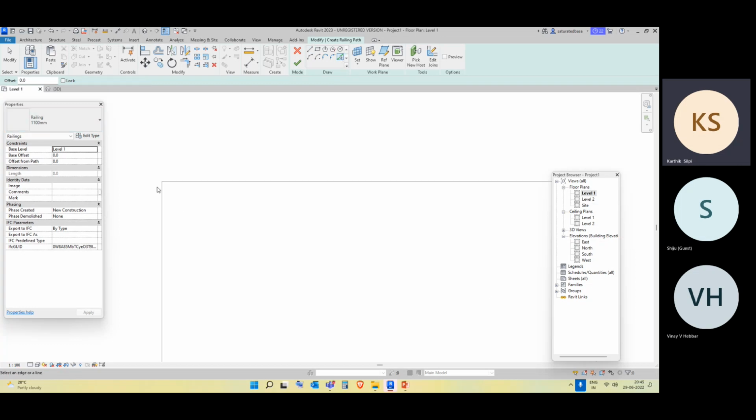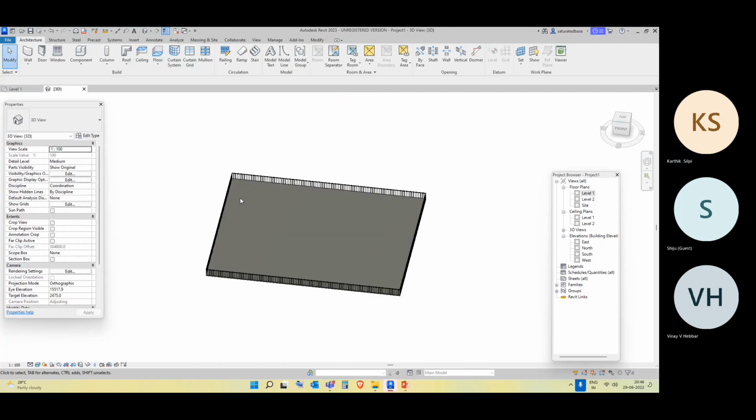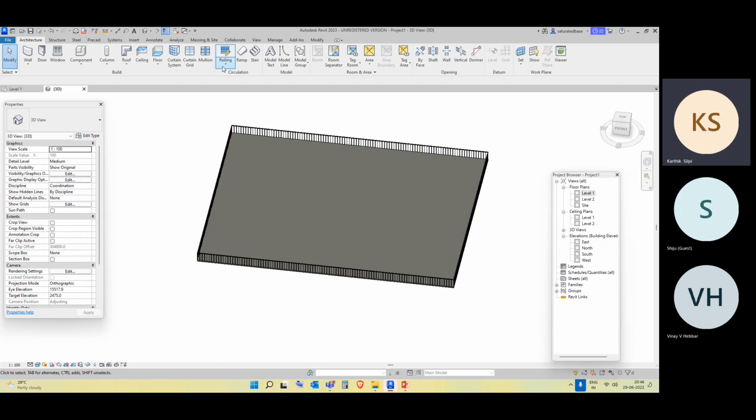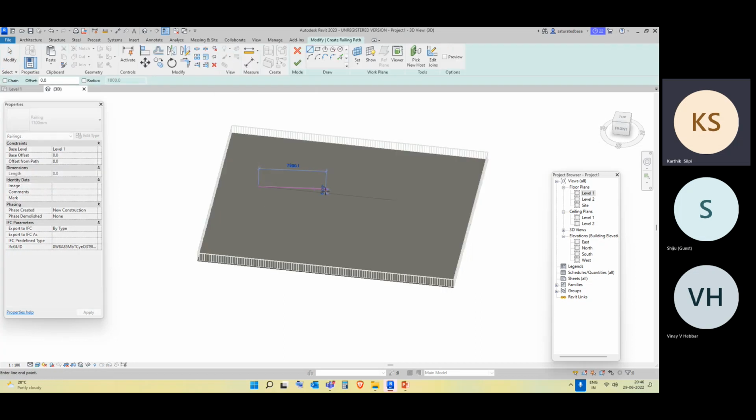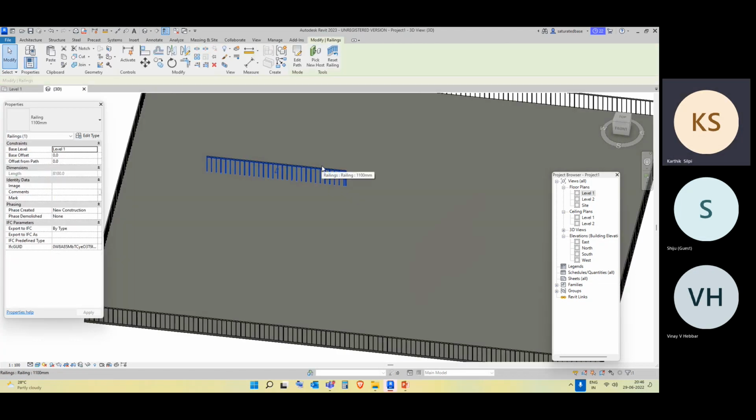And if you're trying to place with the distance somewhat inside, you can just choose an offset. I'll give an offset of say, let's enter. And as soon as I go to this place, you can see we have railing inside. If you want the railing on 4 sides, you can just give it like this, finish it up. Then you have your railing. This can be drawn anywhere. Like say, if you want to draw a railing over here, it can also be drawn. There is no restriction.